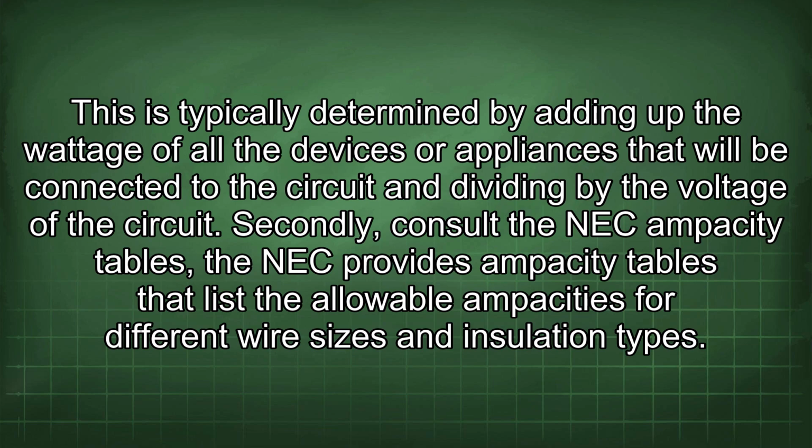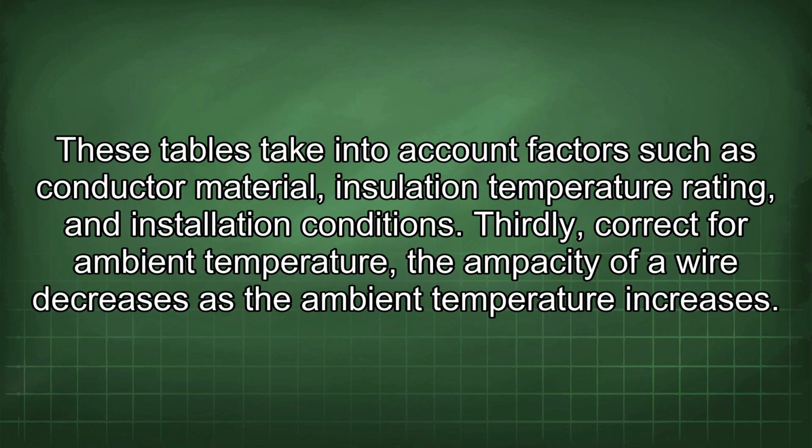Secondly, consult the NEC ampacity tables. The NEC provides ampacity tables that list the allowable ampacities for different wire sizes and insulation types. These tables take into account factors such as conductor material, insulation temperature rating, and installation conditions.